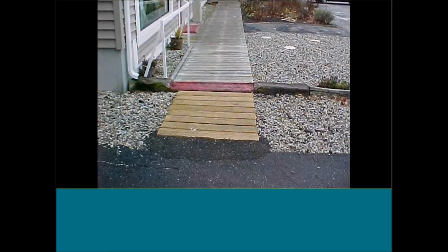Notice the building owner chose the color red to warn people. Unfortunately, red is not visually detectable for those with color blindness or red color deficiency, and does not provide sufficient color or brightness contrast against the wood. Notice the gutter downspout drainage right over the railroad tie that provides an interesting obstacle on wet, snowy days. This whole design was completely redone, and all trip hazards were removed.